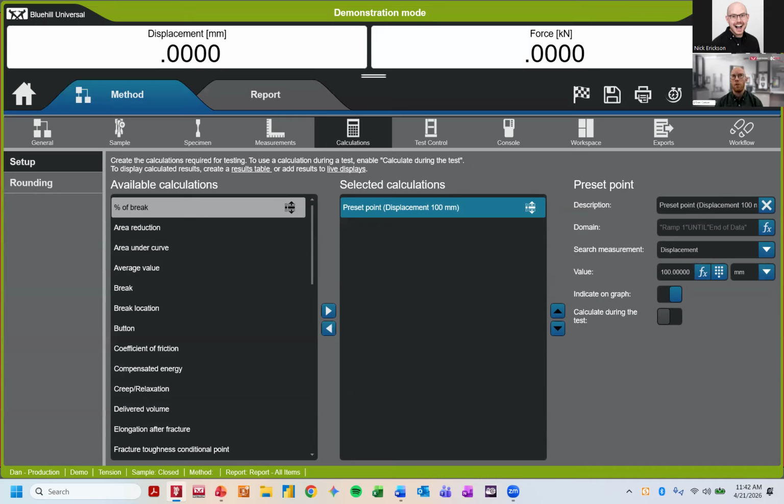So going from a flat specimen to a circular, cylindrical, or bar specimen, or if you have wildly different materials that you're testing, if you have Inconel, if you have copper, two very different materials, how should that play a role into thinking about data integrity. Also, the type of extensometer, physical extensometer, like a traditional clip-on versus a video extensometer.